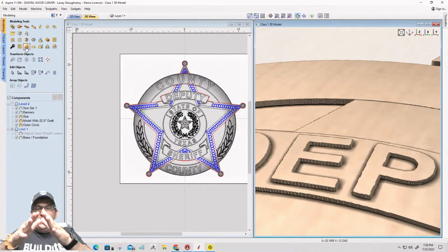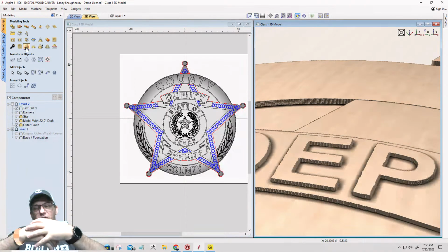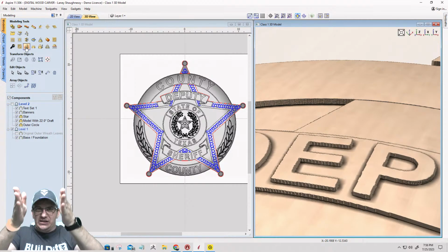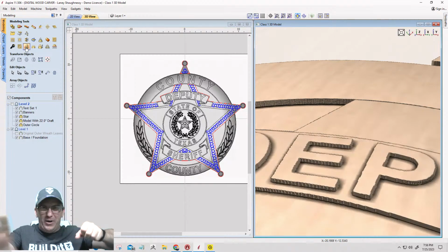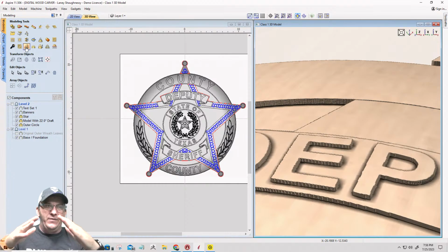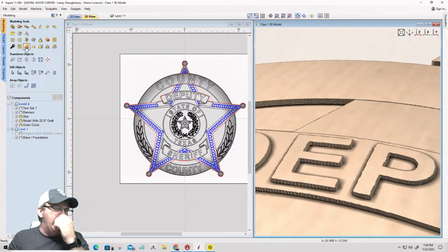Now, technically, a draft is generally used when pouring a concrete foundation, in mold injections and things like that. And basically, it's a slight angle to the edges so that when, especially in injection molding, these parts get created, when that mold opens, they fall right out, you know? There's just a slight angle to the edges instead of being straight up and down where they could actually lock with each other to where it's hard to get that part out of that mold kind of thing. It's called a draft. And sometimes in slabs and stairs, on slabs you add a draft to that concrete step or whatever.